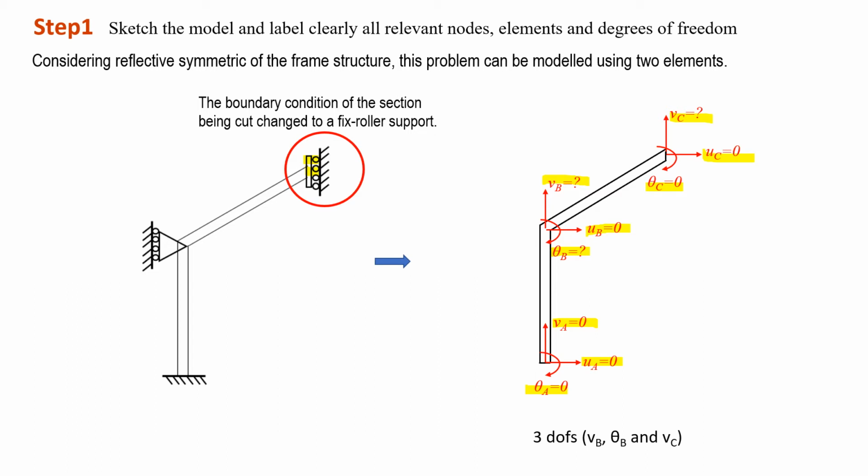Please remember, pin roller support and fixed roller support are not the same. For pin roller support, theta still exists, meaning that it can still have rotations. But for fixed roller support, it cannot rotate. So the rotation will be equal to 0.